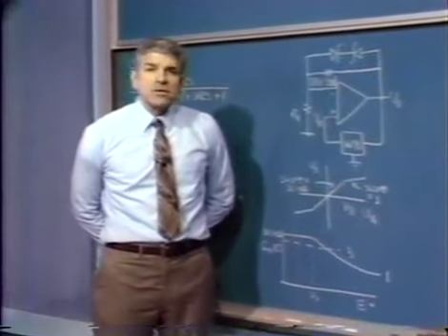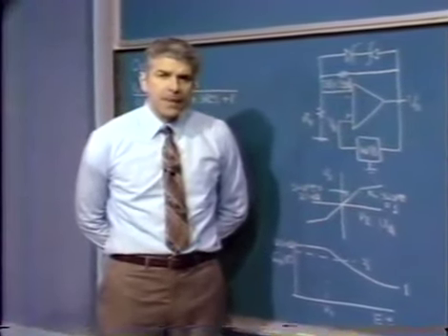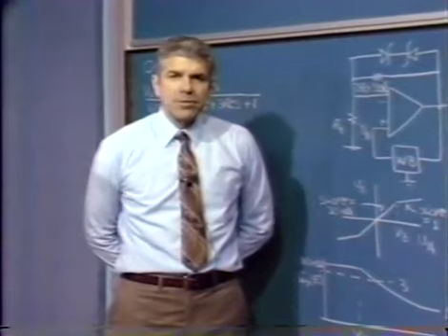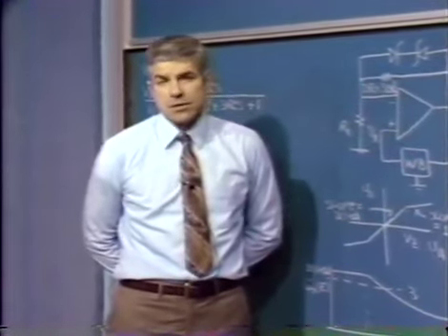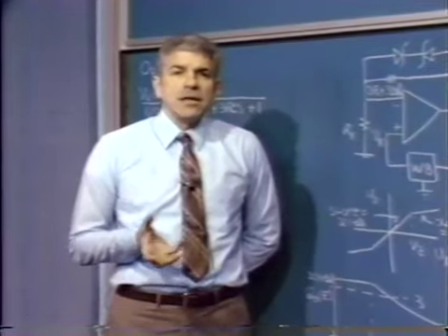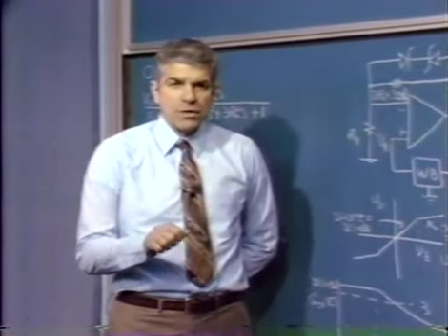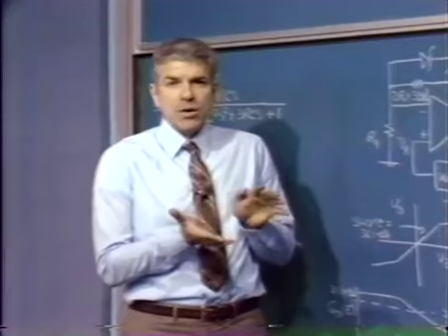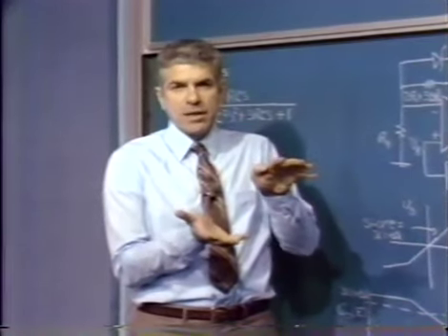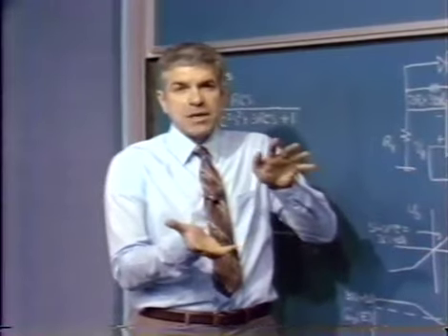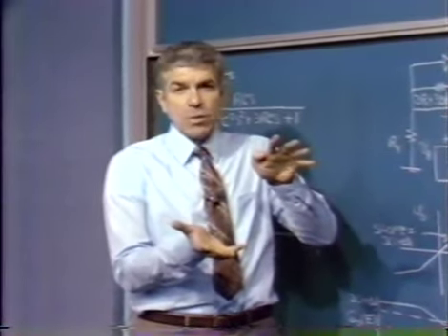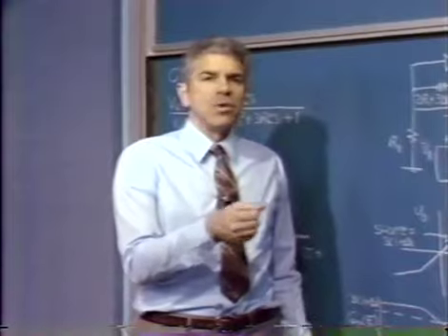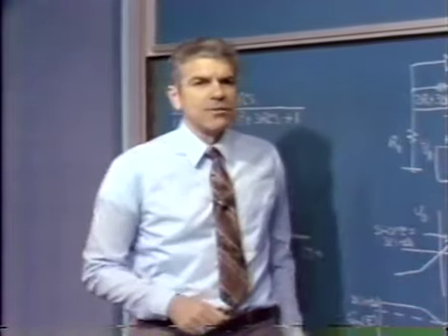We could, for example, consider taking our oscillator and maybe have a potentiometer that allowed us to adjust gain. And we could look at the output of the oscillator on an oscilloscope, and if we found that the amplitude were shrinking or were smaller than we wanted it to be, we might up the gain of the operational amplifier. That would presumably move the poles of the system either into or toward the right half plane. If we moved them into the right half plane, the amplitude would begin to grow. We could let it grow to the amplitude we wished, and then back off a little bit on the potentiometer. And hopefully by us playing servo mechanism, we could keep a constant amplitude oscillation.